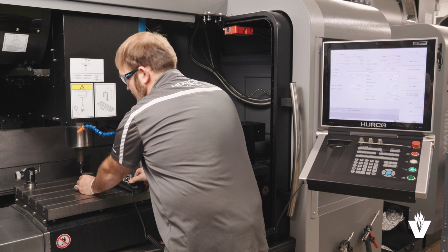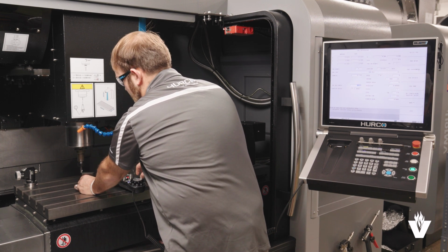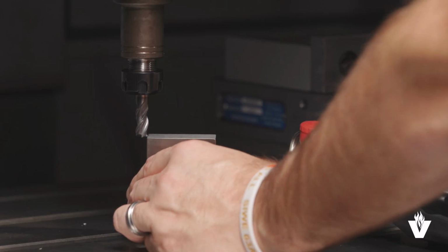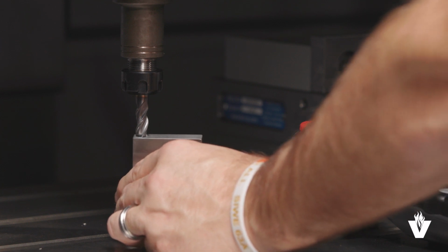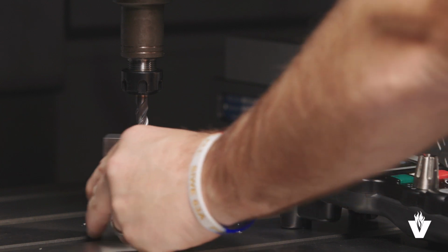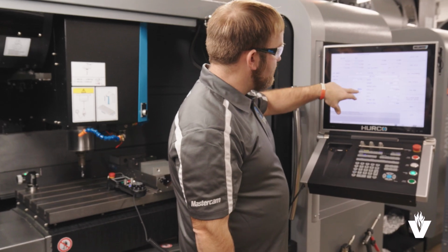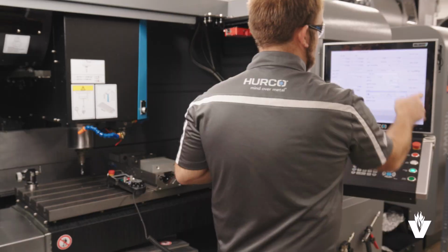Once in position, I will back it down one more click and then go to the smallest increment on the control. So instead of moving 10 thousandths at a time, it will move 1/10 of a thousandth every click of the knob. Now I'll bring the block next to my tool again and raise up until it will slide under once more. Once it does, we hit store position and it stores that as a tool length.